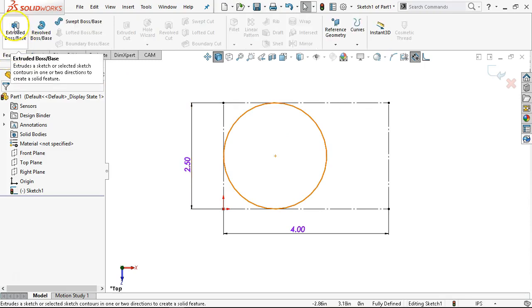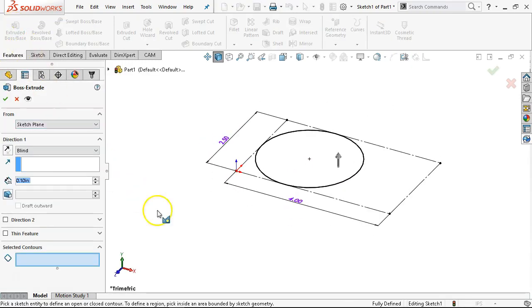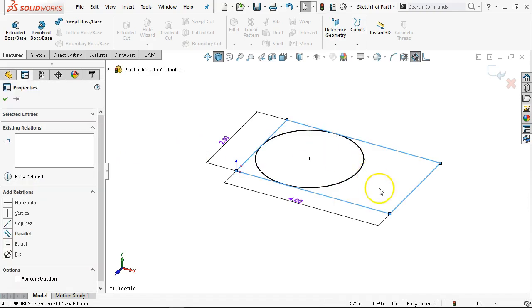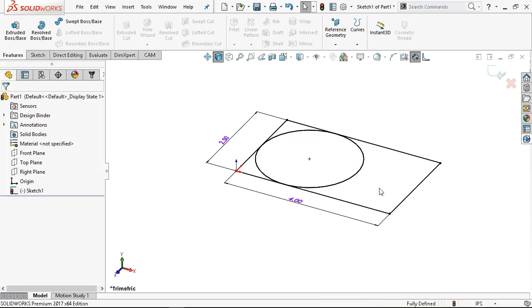And with one object on top of the other, let's go ahead and try to extrude it. It does not automatically go to extrude, even though I think I only have 1 object. No, I have 2 objects there because I made them co-radial. And so this is where the selected contouring region comes in and says you have to pick what do you want. And the center lines are not valid. And in most cases, we'll do a quick comparison. Control Z, no, probably didn't want to do that one. Oh well, we'll pick it up here in a minute.